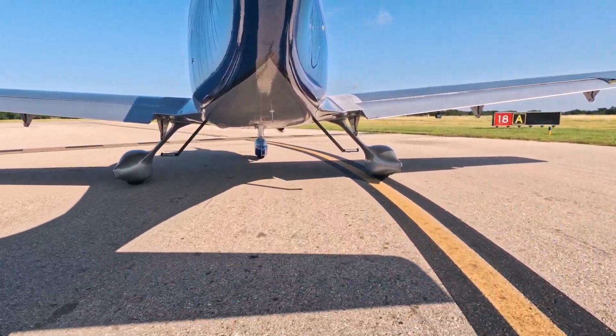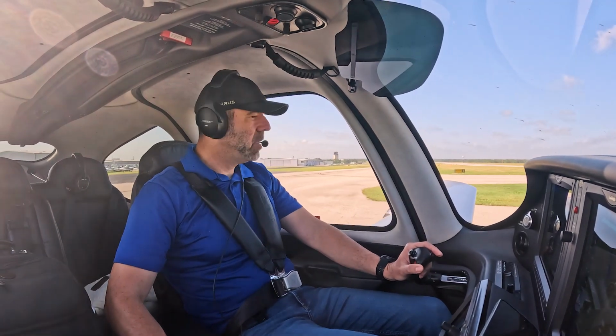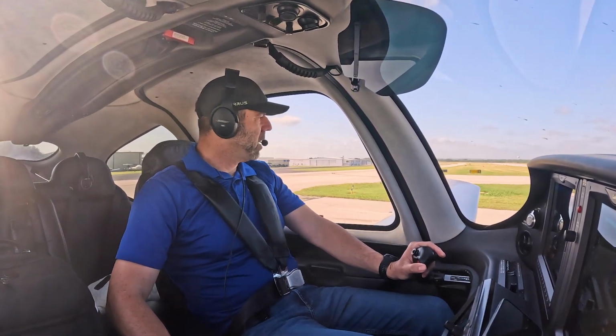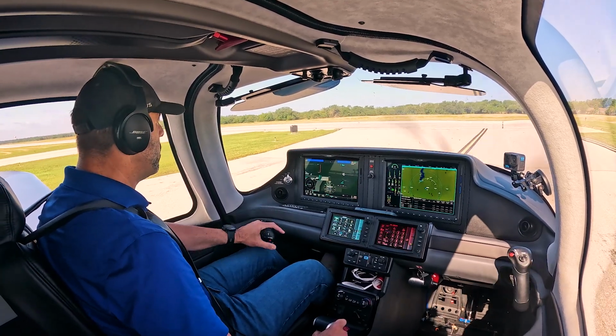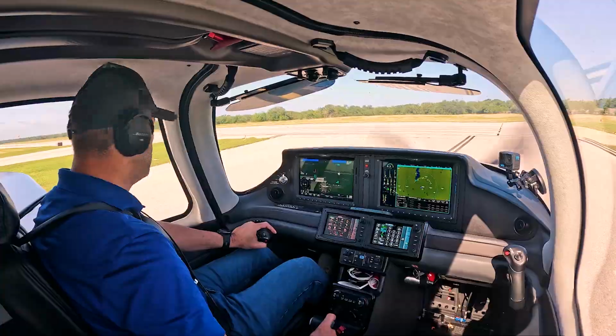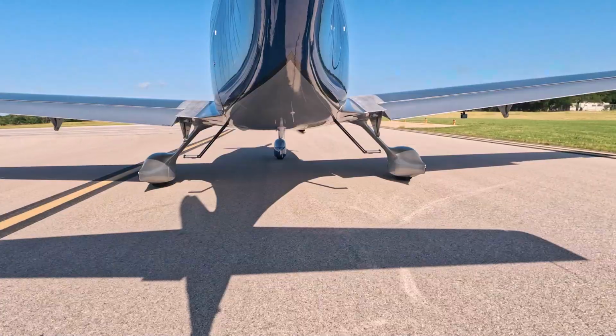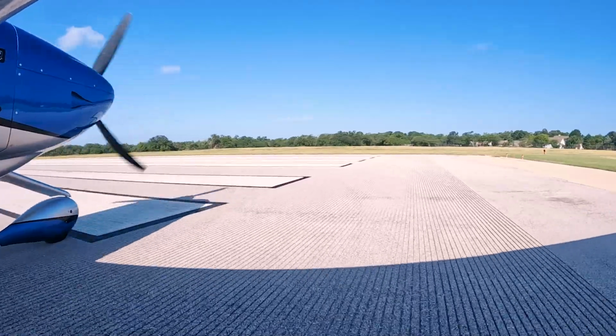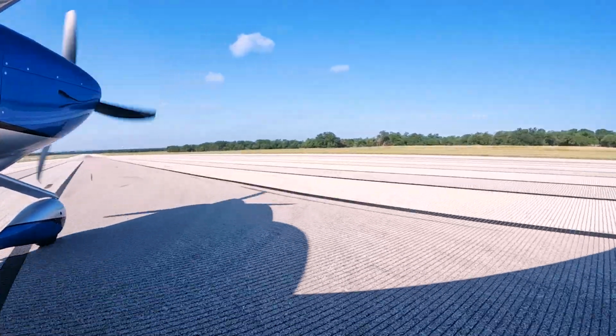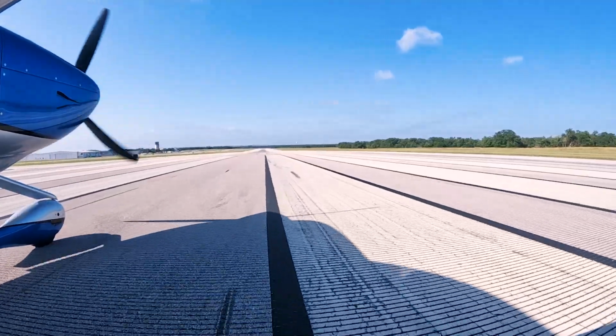All right, here we go, guys. Final is clear, runway is clear, and you can see that windsock. Yeah, we've got a good little crosswind from the right. All right, so full deflection into the wind, that's to the right. We use all the runway we can. Now that wind's gusting, we've got a good amount of wind, so we're probably going to rotate a little bit sooner. So get on center line. Make sure you're on center line before you depart.